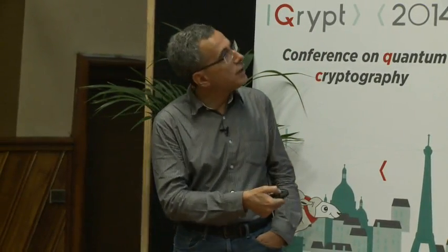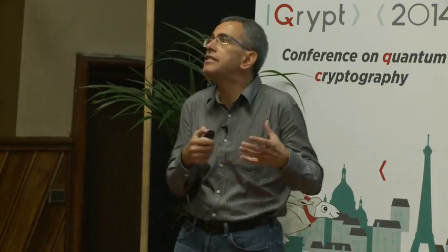Okay, so here is a very quick introduction to quantum dots. This is a cross-sectional TEM picture of a quantum dot. It essentially is an island of semiconductor embedded in a higher bandgap semiconductor. In this case, this is indium arsenide surrounded by gallium arsenide. And what makes it special is that even though it has a large size, consisting of 10^4 to 10^5 atoms, it nevertheless exhibits nicely discretized electron and hole states and has a discrete and anharmonic optical spectrum.